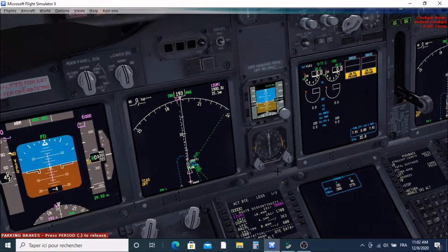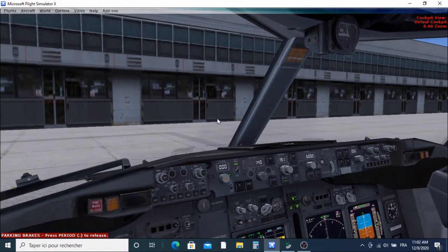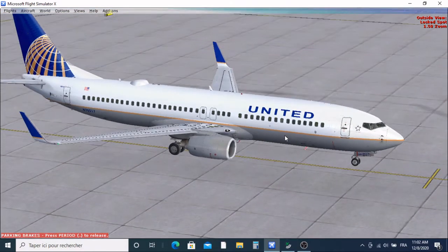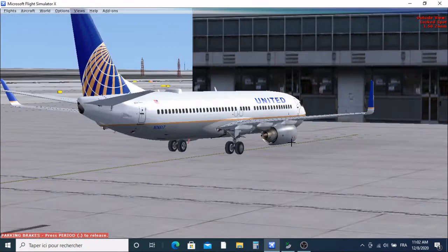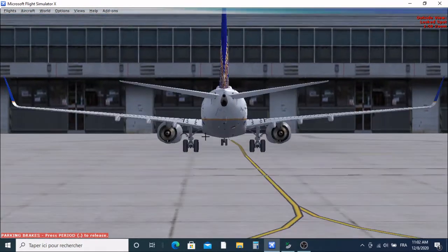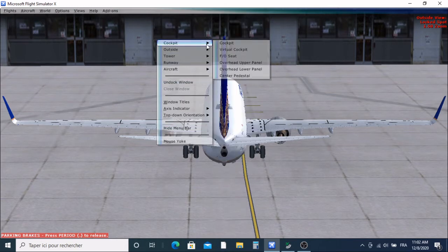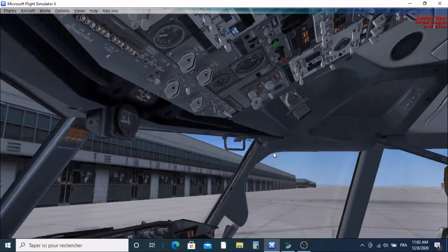And ground, cockpit. Hi, Captain. We're all set to go up here. We've been cleared to push and start at your discretion. Right now, ready for push. Power area clear, doors closed. We are ready for pushback. Expect... brakes. Parking brakes. Okay, parking brake is on, cleared to push.